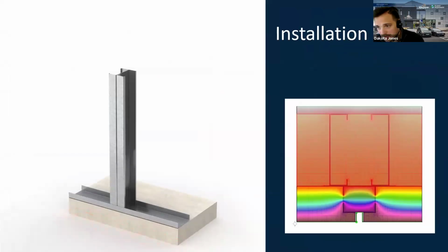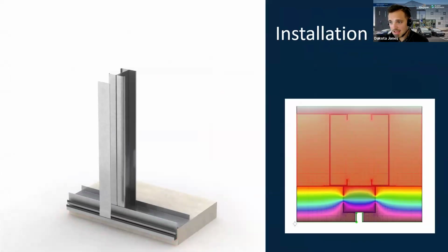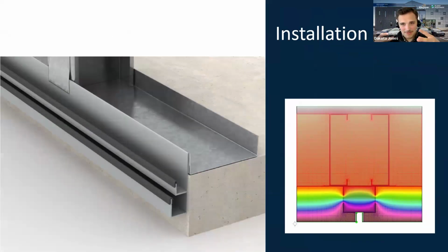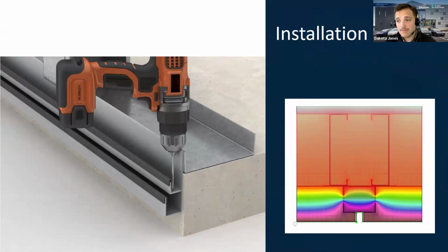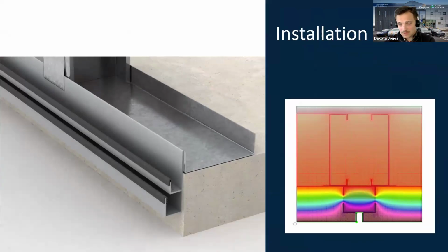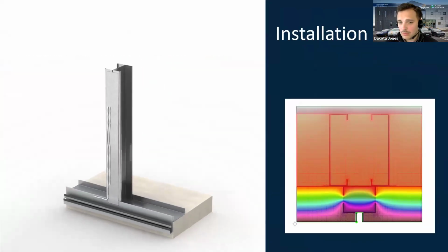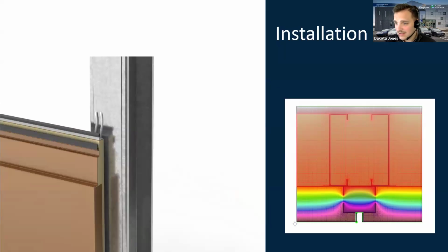Now, hopefully this should answer any lingering questions of how this thing goes together. Well, let's look at this. This is, again, as complex as it gets, where two IMPs meet butt to butt after the 53 feet of length. What we have is a double stud condition with a mending plate to give us a nice flat surface to essentially glue our IMP on using something called a non-skinning butyl. It's essentially a silicone-like material that never quite gets dry and allows the building to move a little bit while keeping our air and moisture sealant nice and tight.